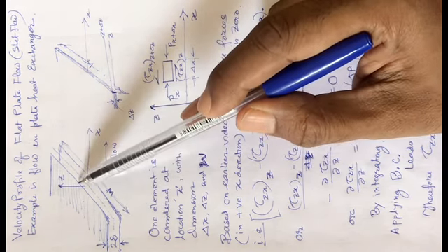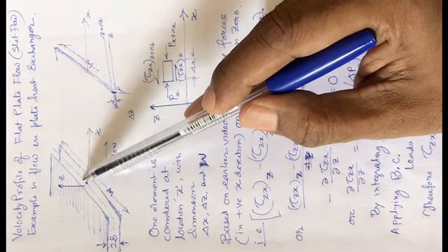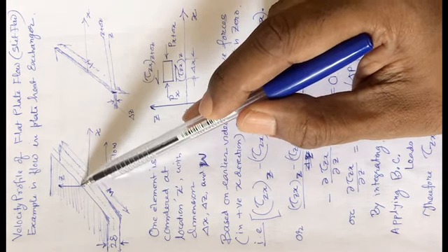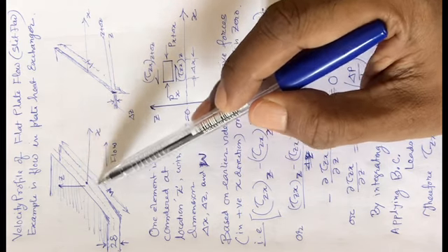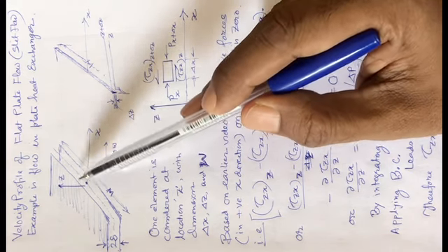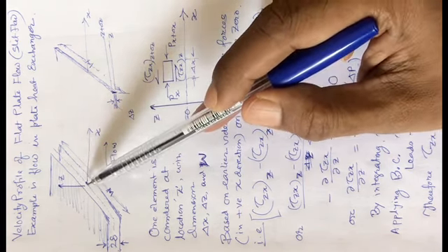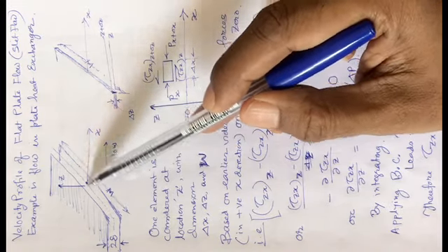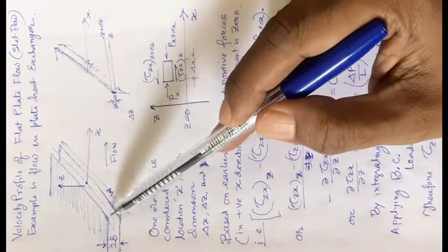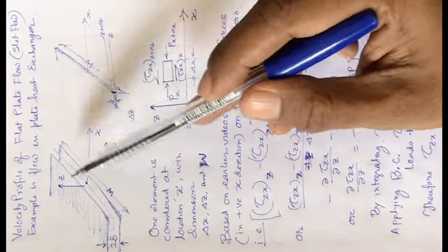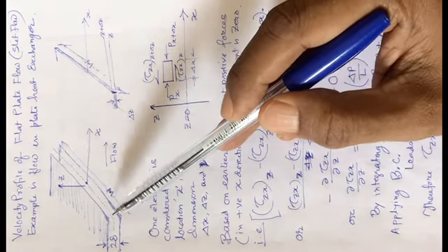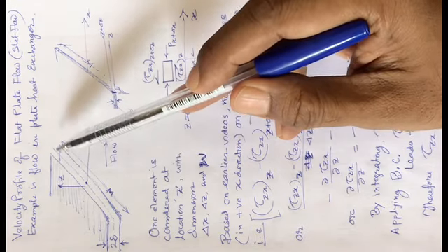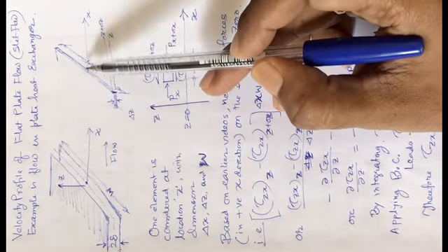At this center the velocity will be maximum, towards the top and towards the bottom the velocity is decreasing, and at the interface with the top plate and bottom plate the velocity becomes 0. So the midpoint is of concern actually. See this, there is an axis passing through the midpoint and this central plane. So fluid moving at the central plane will be moving at the maximum speed.